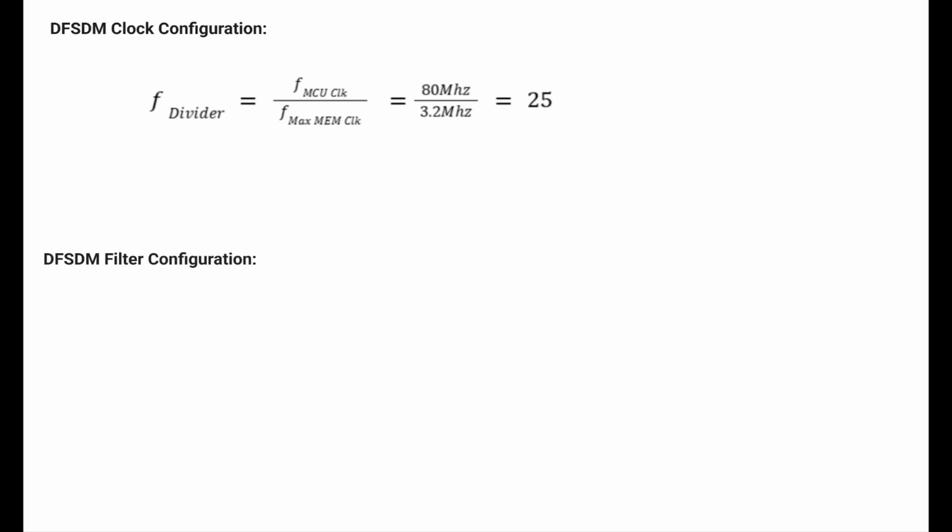There are three important parameters that must be set before using DFSDM. Two of them are low pass filter parameters, FOSR and IOSR, and one output offset value called right bit shift. The filter parameters control the decimation process of the audio signal, while the right bit shift helps scale the final output to avoid overflow.